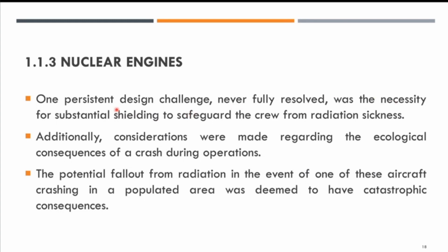the necessity for substantial shielding, because nuclear operation will produce radiation, so we do not want the crew to get sick because of the exposure to radiation. Additionally, considerations were made regarding the ecological consequences, like what happens if a nuclear powered aircraft crashes somewhere, and the whole area will be a disaster.